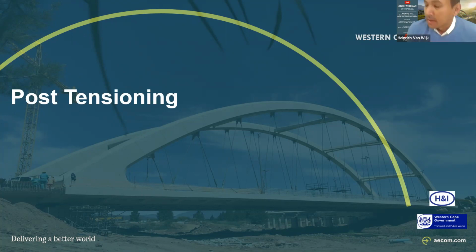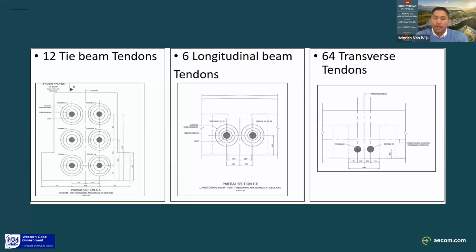Okay. Thanks, Abe. I'm going to carry on discussing the post-tensioning activities of the main deck. And as Abe mentioned, the bridge is maybe not that conventional for a tied arch bridge, because the deck, which is a tension element, is made up of concrete. So for the deck to be able to take all of that tension induced by the arch, you have to post-tension or pre-stress the deck, so that this concrete element is always under compression.